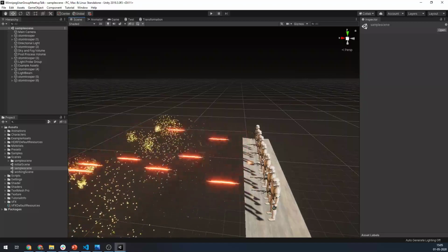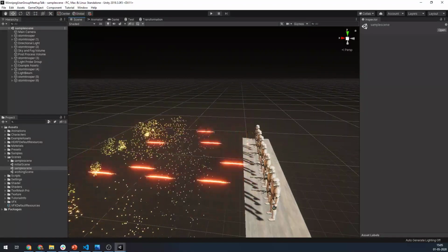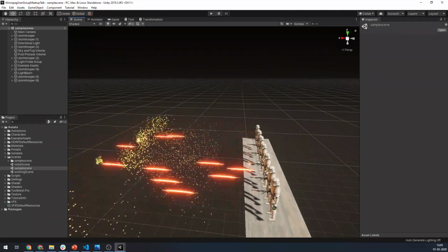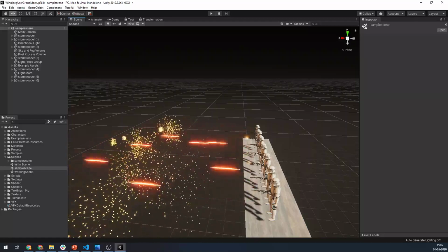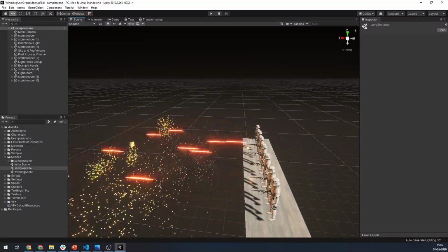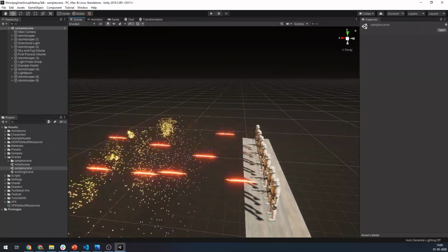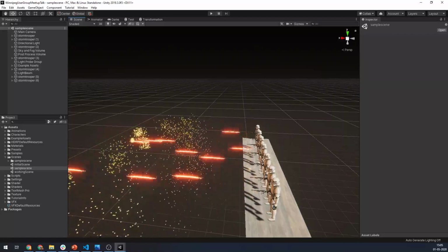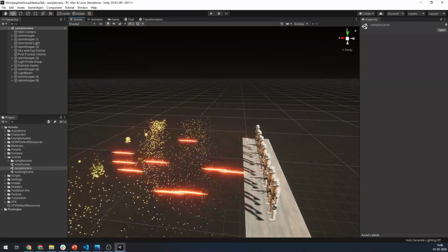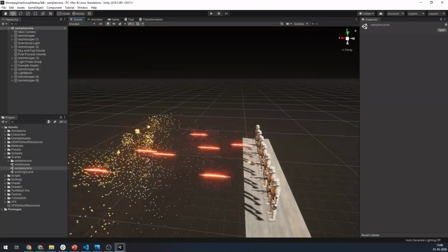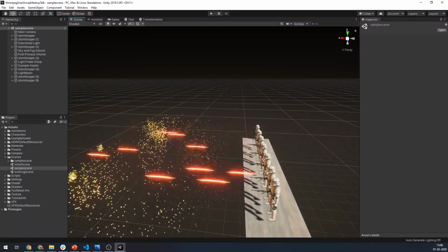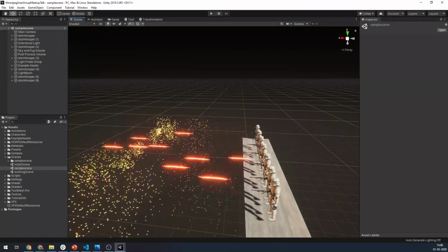Blaster effects are a great way to teach VFX graphs since it teaches you how to create all kinds of other effects as well. We'll also be talking about GPU events, which is very powerful to string effects together so that different aspects or different effects are spawned one after the other. We'll split the blaster effects into three parts. One, the initial blast that you see right here. You see the little sparks that are generated when this plasma energy is being created. The second part would be generating the plasma beam itself. And finally, we'll look at explosions.